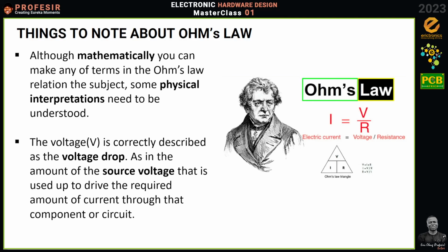Now, take note that there are situations where, for instance, if I have a 9-volt power source and a 9-volt lamp, I can just connect them directly. So technically, the voltage drop also becomes the EMF. So there is that situation, but the statement of Ohm's law is about voltage drop. It's not about EMF or the source voltage.